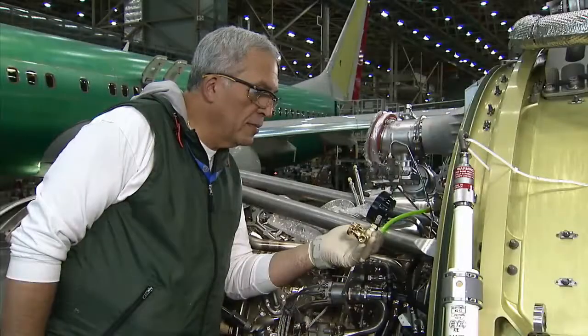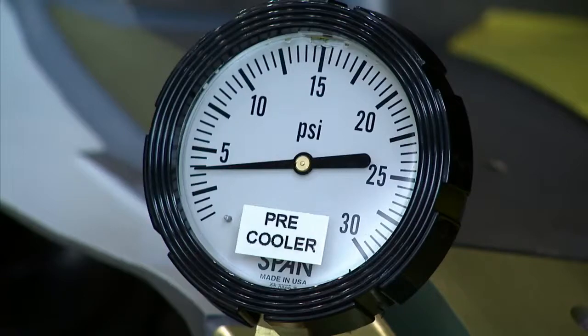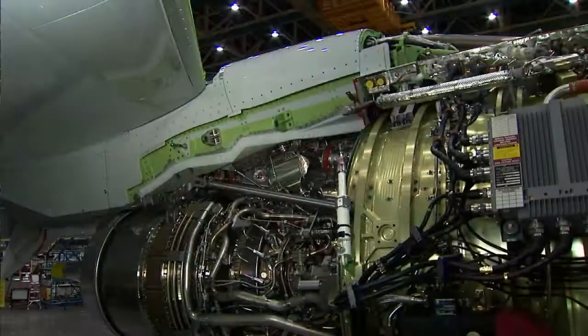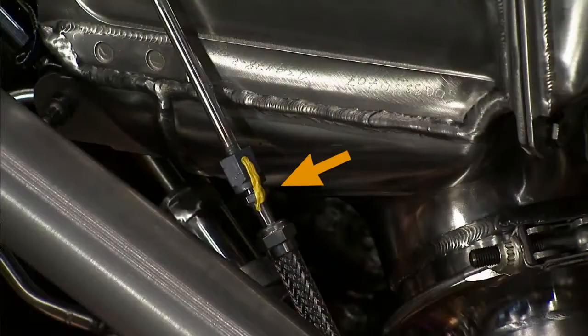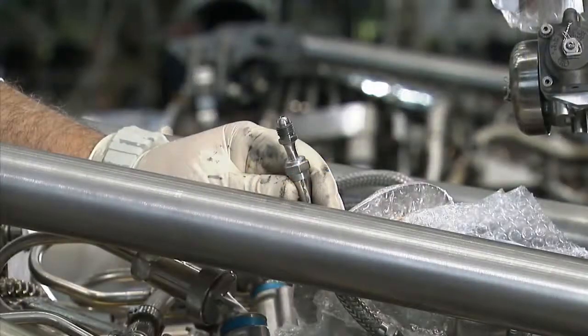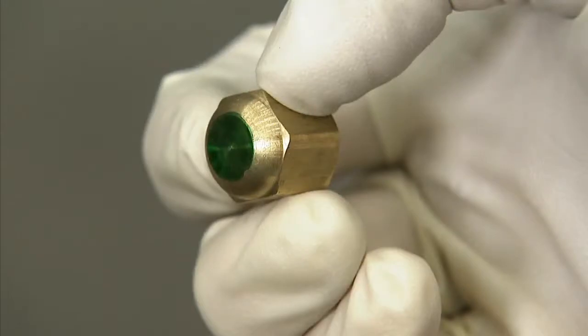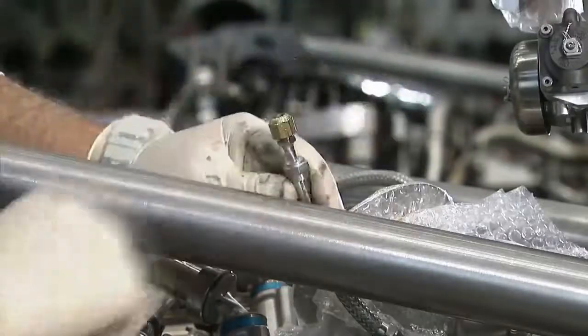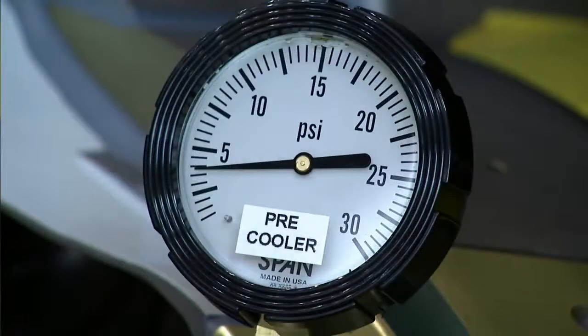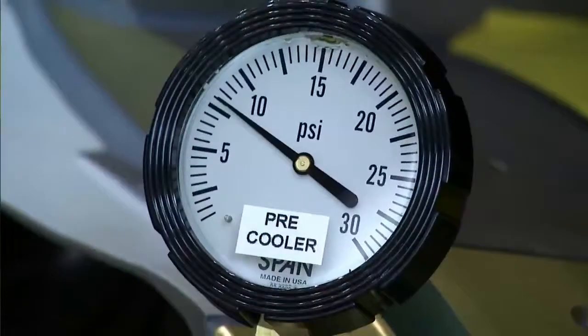If the pressure on the PCCV test gauge is low, this may indicate a leak or faulty part. To eliminate the 390 sensor as the source of the leak, disconnect its control pressure line up near the right side of the pre-cooler and cap it. If the control pressure is still low, the problem is with the PCCV or its control line. If the control pressure is now good, either the 390 sensor or one of its control sense lines is leaking.